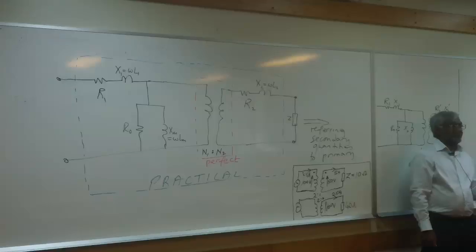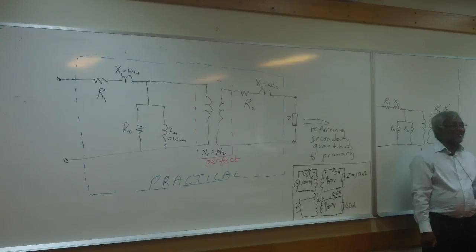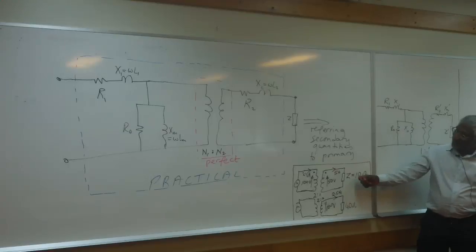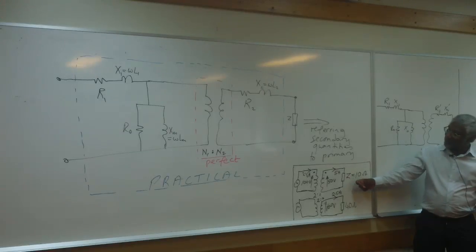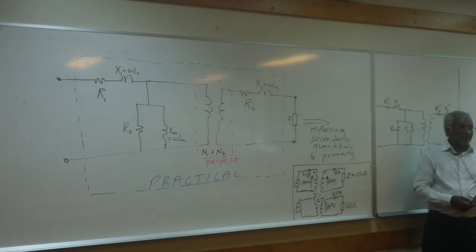It's the volts over ampere. Yeah, you're right. It's volts over ampere, but I wasn't looking for that. I said, what factor do you multiply by to get from the top one, which is 10, to the bottom one, which is 40? The square of the turns ratio, right?